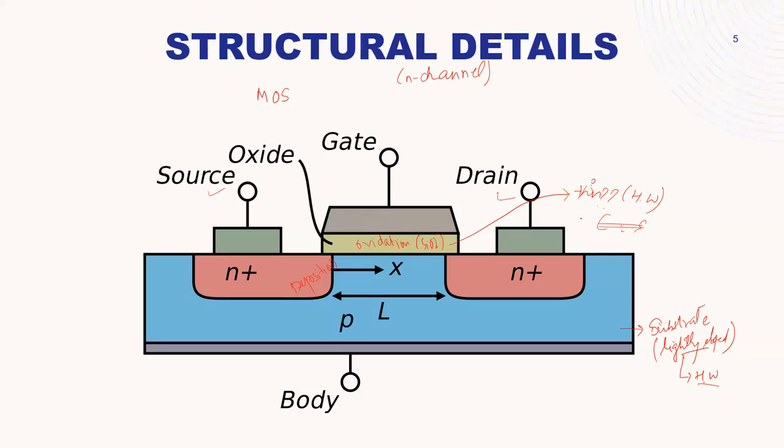These electrical contacts of source and drain happen at the very, very end. But before this, the oxide layer is grown throughout this region. And then you chip off the oxide, or I mean, you etch the oxide from places where you have the source and drain.